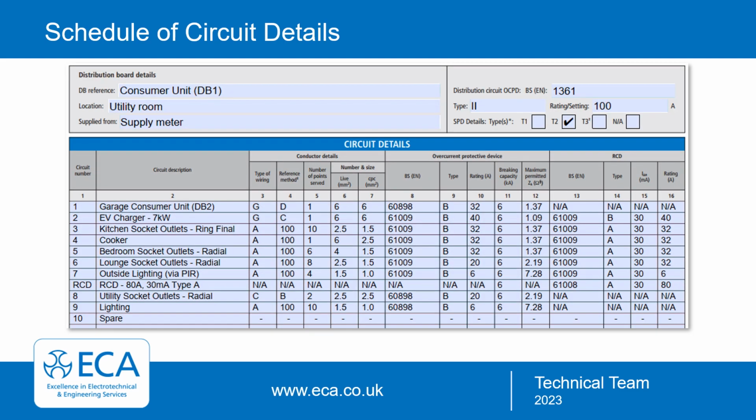And now let's look at the schedule of circuit details. So this is the first part in a 2-part form. We'll look at page 1 here, the circuit details, in just a bit more detail. So where an SPD is installed at the origin or built into the consumer unit or distribution board, this is to be recorded under the SPD details.